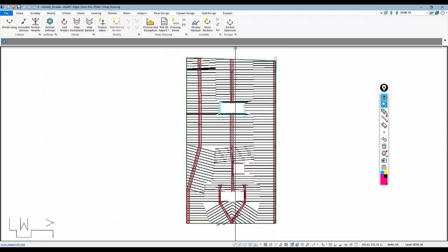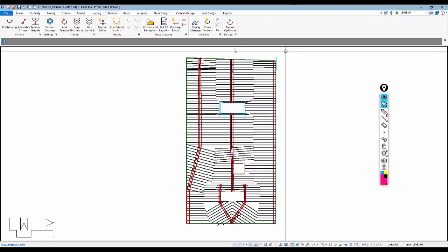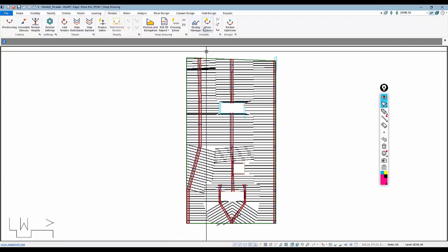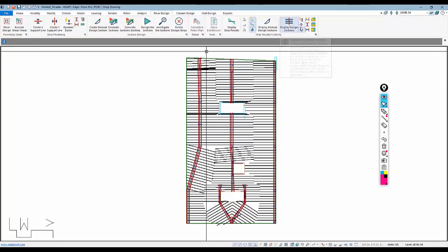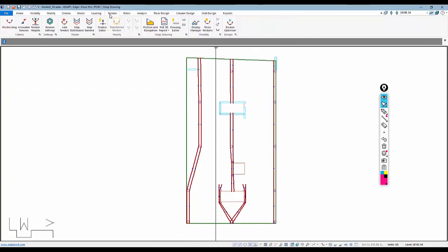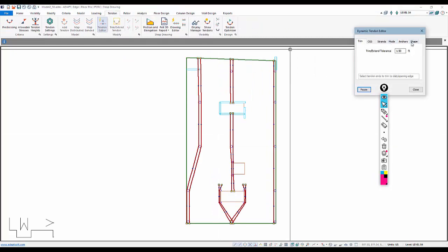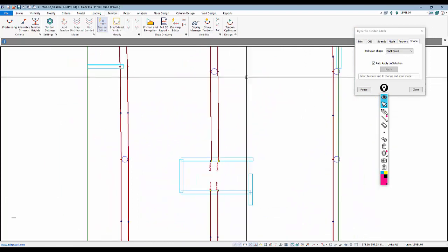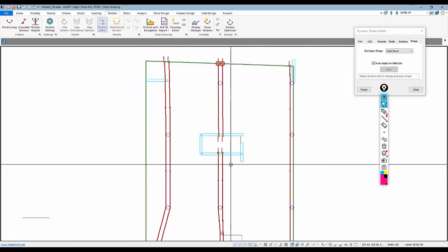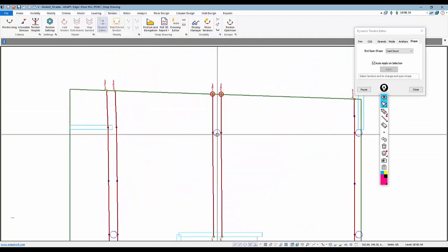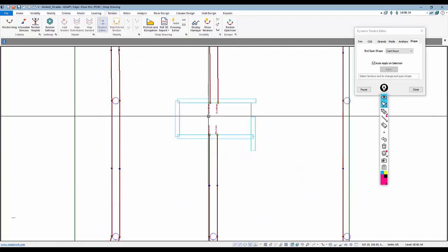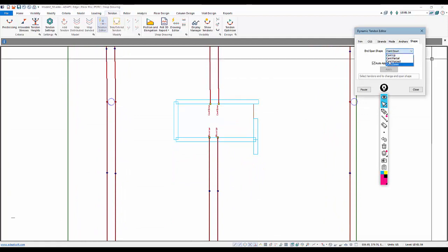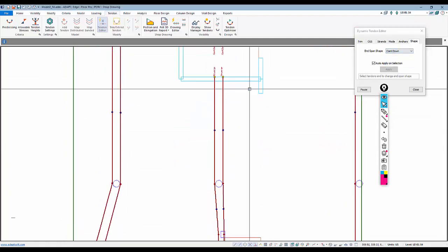And the next thing we're going to do is come back and adjust the cantilevers again like we did for the tendon on the left. So I'll turn off my strips. I'll go over here to Tendon Editor. The first thing I'm going to do is modify the shapes. So this is reverse parabolic. I'll modify that shape. This is already a cantilever down shape. We're actually going to want to change that. We don't have a reverse option here, so we'll come back and manually change that.